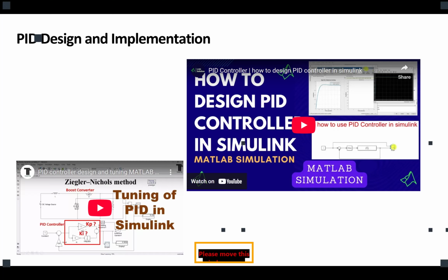So we are not going to see a very high rate of change in our variables, ergo in our error signals. What does that mean? That means practically, if we can't handle that, we could get rid of the derivative part, because the speed is already defined. So it won't do much for us.